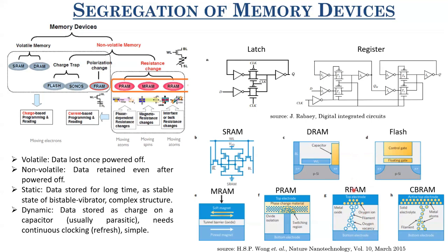Now, if you apply a negative voltage, the positive voltage will repel these oxygen vacancies, while the negative voltage will attract them. So when you apply negative voltage, oxygen vacancies get attracted towards it, and hence some amount of insulator is uncovered. Now if you apply reverse polarity, let's say positive voltage, the oxygen vacancies which were close to the surface will start going towards the bottom electrode. And again, you'll have a conduction filament of these vacancies connecting the top electrode to the bottom electrode. Therefore, the resistance will reduce.